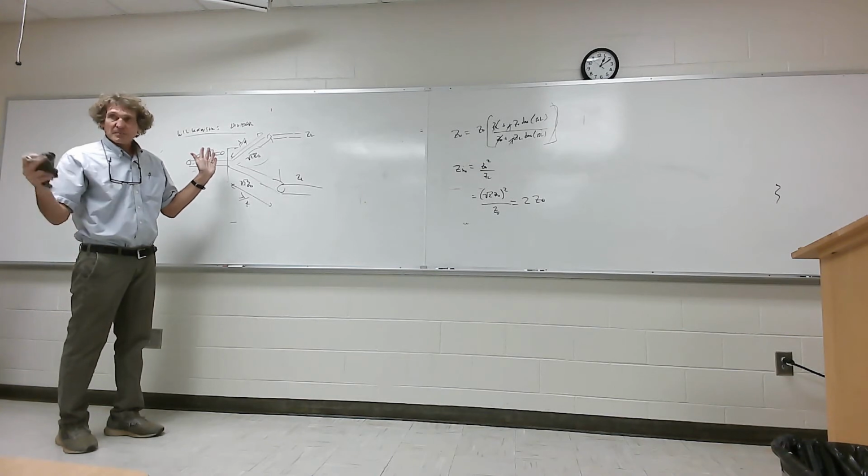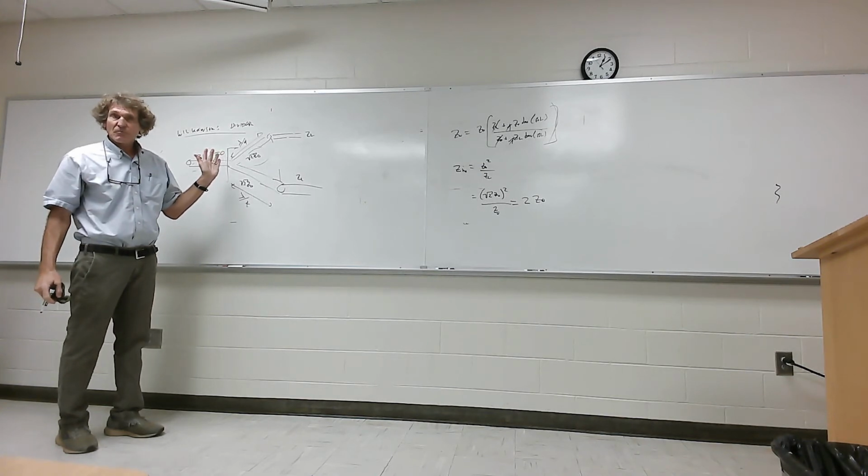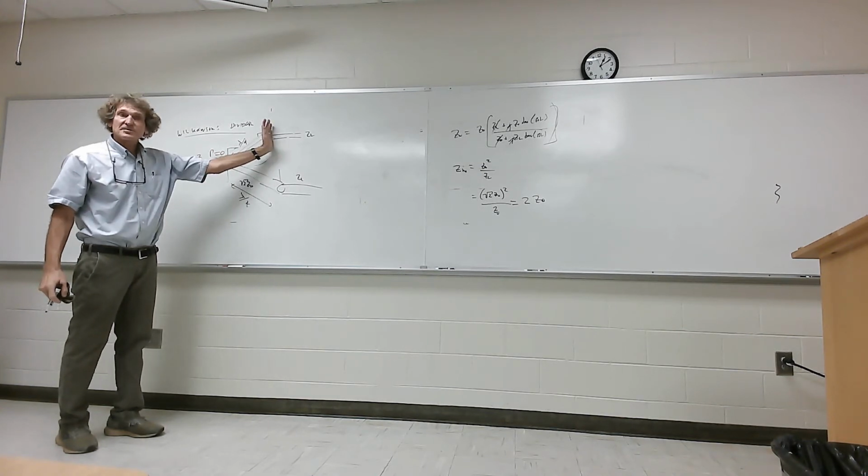Now, here's the thing about this divider, and I'm just leveling. This is great. If you're at an exact frequency, it works. But remember, that quarter wavelength is quarter wavelength for only one frequency. So any kind of frequency spreading of significance, and this thing doesn't work worth a darn.